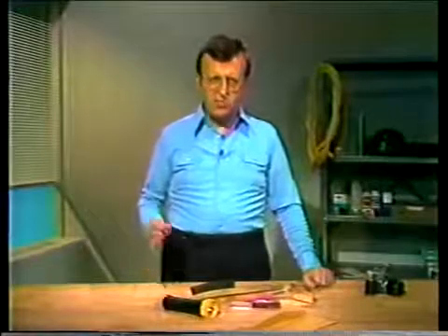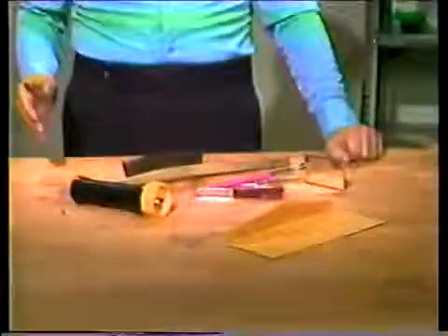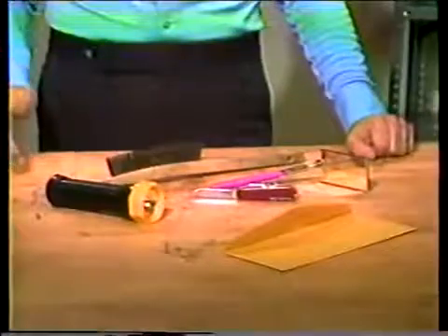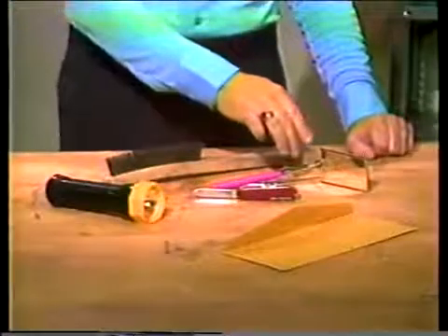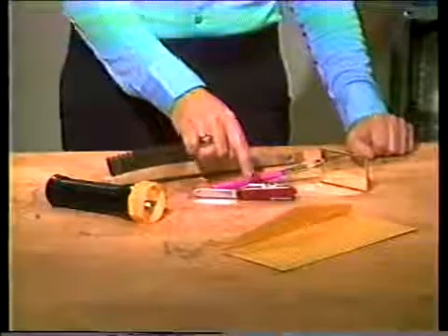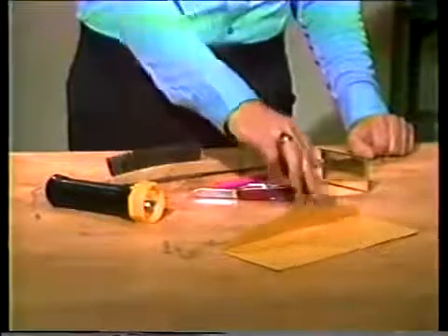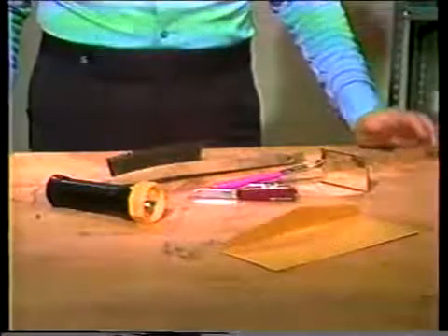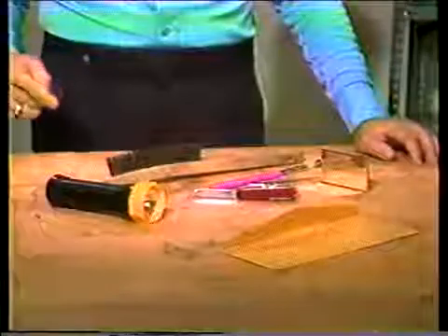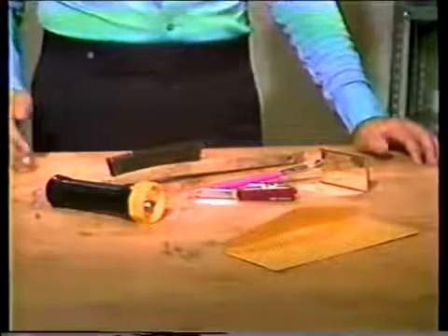Besides people, waterside inspection requires tools. The tools you need are the same as those used in fireside inspection: a flashlight, an inspection mirror, a knife or scribe tool, and a wire brush. Several containers or envelopes will also come in handy. These can be used to hold samples of deposits that might be found. Later, these samples can be analyzed to determine their nature and their cause.